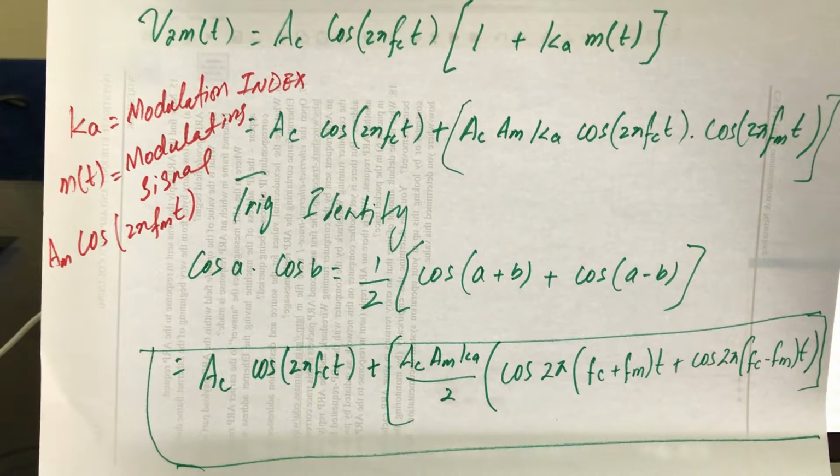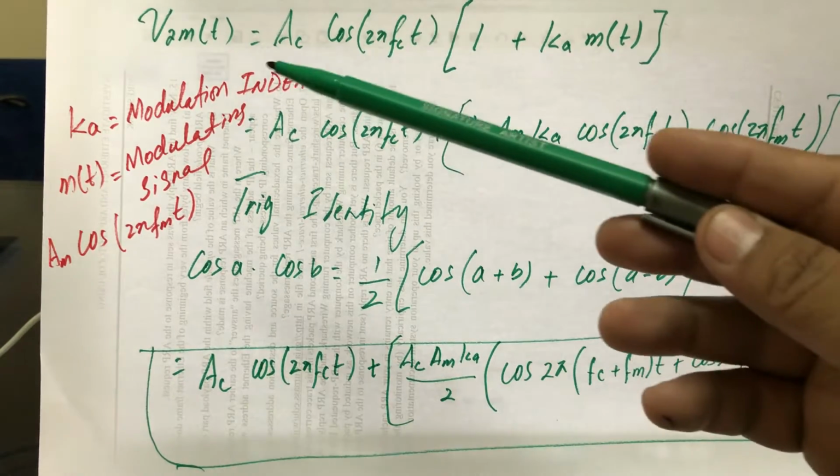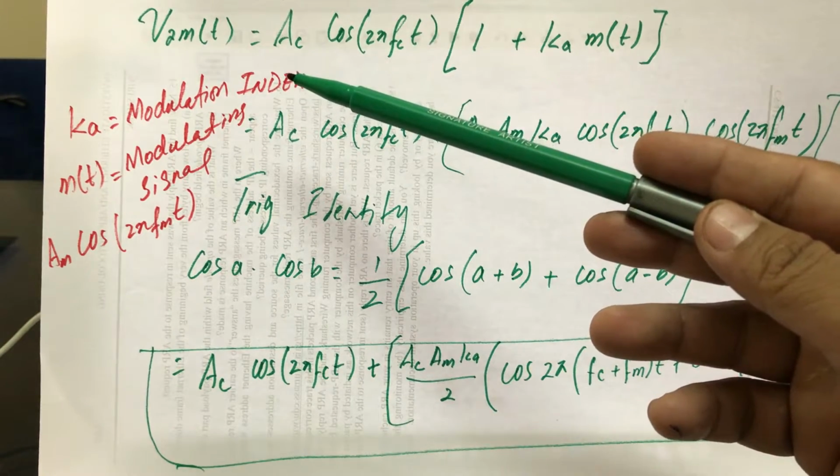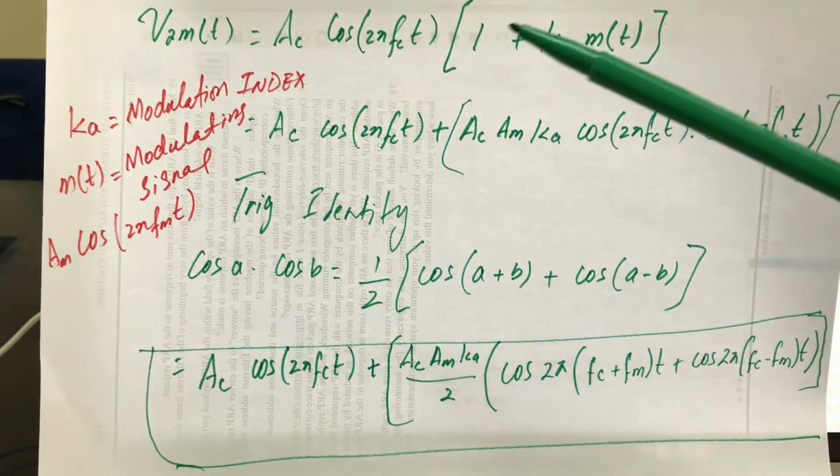But sometimes there could be overmodulation in the system, and that overmodulation can be defined when your modulation index is more than 1, so anything above 1. So this value can vary from 0 to 1, and if it's less than 1, then this signal is undermodulated. This factor will tell me this. And if it's more than 1, it's overmodulated.